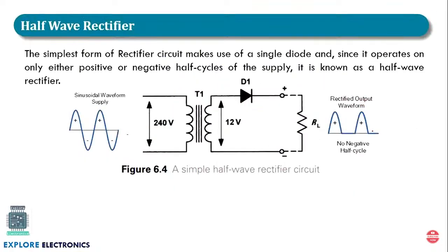Next we have rectifier circuits. By using this diode functionality, we can have different kinds of rectifiers to convert an AC signal into DC signal. The first one is the half wave rectifier. What is a half wave rectifier? A half wave rectifier is a device. It is going to convert an AC into pulsating DC, but the output of the half wave rectifier will be half cycles if we compare to the signal at the input. So let us understand what is a half wave rectifier.